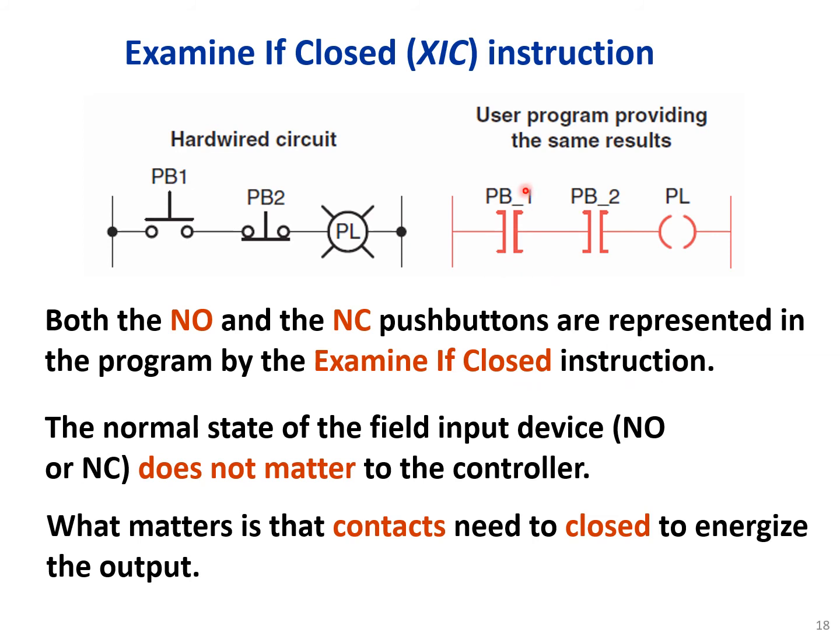Okay, so this one is XIC. This one is XIC. This one is also XIC. Yes, but the physical push button, one of them is normally open and the other one is normally closed. But in the programming, we could represent both of these by XIC.